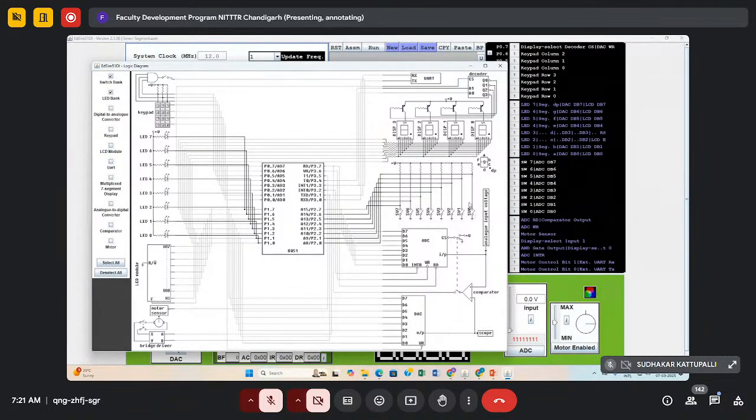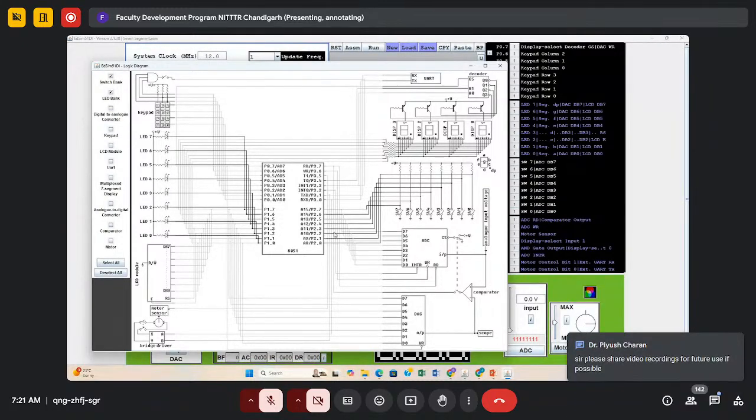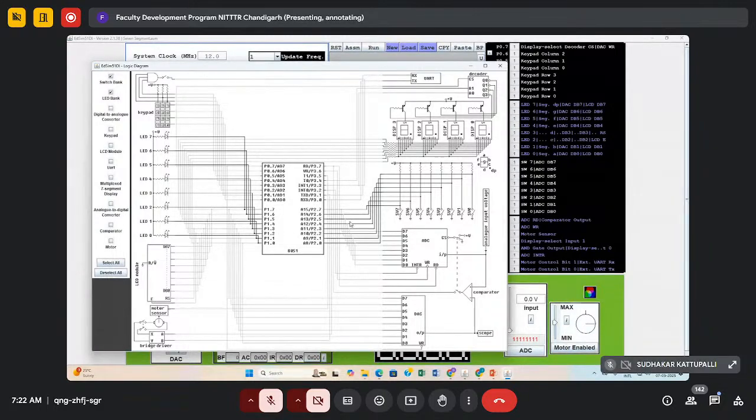So suppose I want whichever switch is on or closed, the subsequent number of LED should get on. So what we were doing was writing the data in port 1. Here, if it is 0, suppose switch 7 is closed, so we'll get 0 on pin number 7. What we'll do is read the data from the switch and just move it directly to the LED. Mapping. Just map it 1 to 1, right?